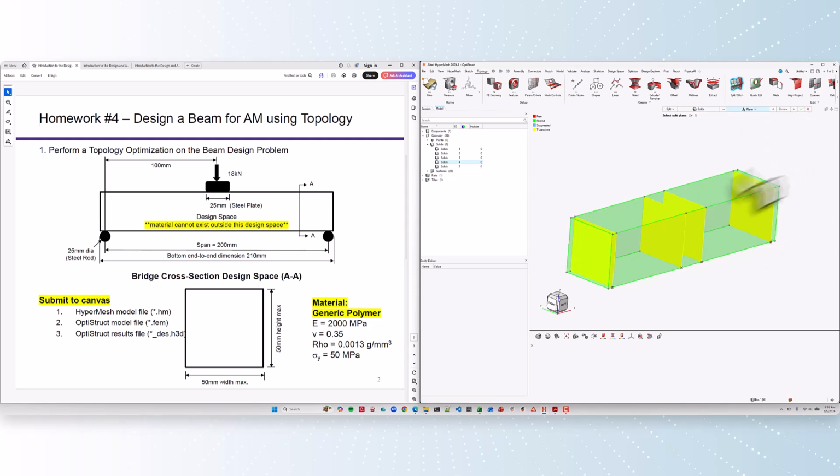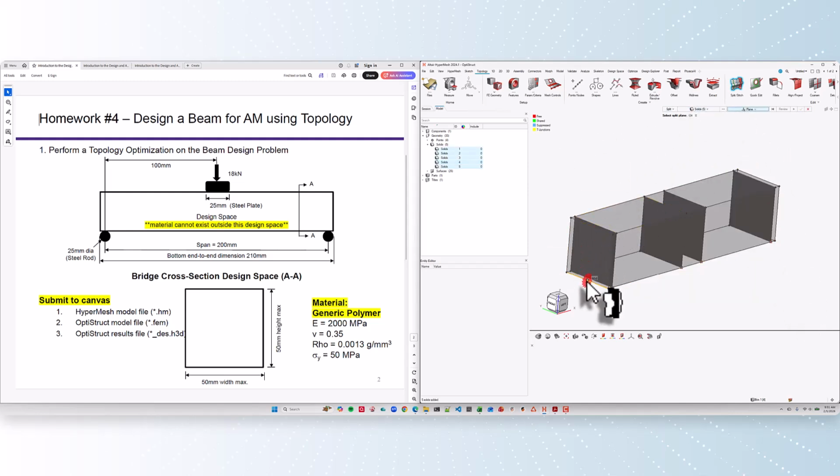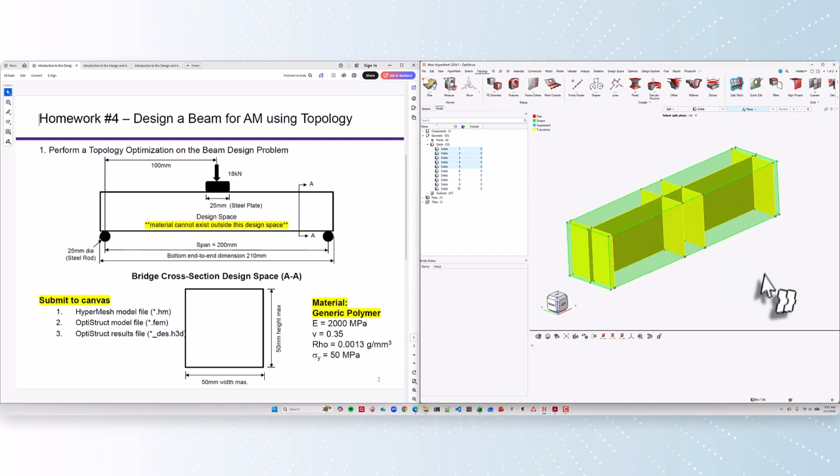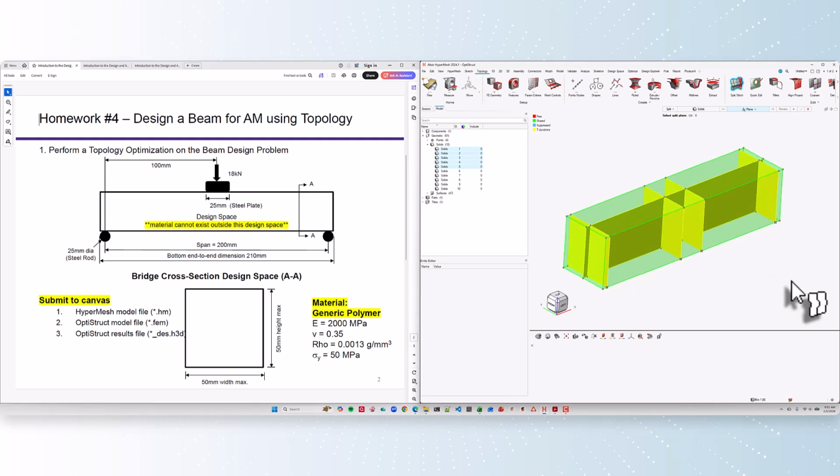Okay, one last thing that I do is, and I didn't need a point for this because it automatically snaps to midpoints, as you see here. So I'm going to pick solids again, but I'm going to pick all of the solids. And then the plane, I'm just going to snap it to the midpoint along the length. I want it cut right down the middle there. And now I kind of have edges everywhere I need things in order to apply boundary conditions.